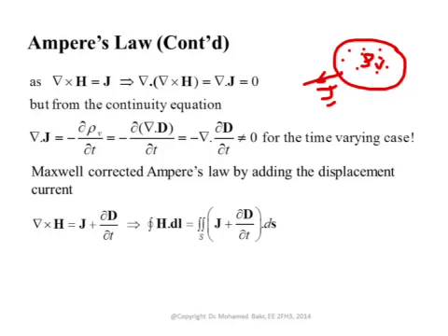So when there is a time variation of the fields, this is equivalent to a current flowing, called displacement current, and this is really the current that's flowing inside the volume of a capacitor. The current flowing inside the volume of the capacitor is not due to movement of charges, but rather it is due to the variation of the electric field inside the volume of the capacitor. And now we can correct this. This is Ampere's law, the modified Ampere's law in the differential form.